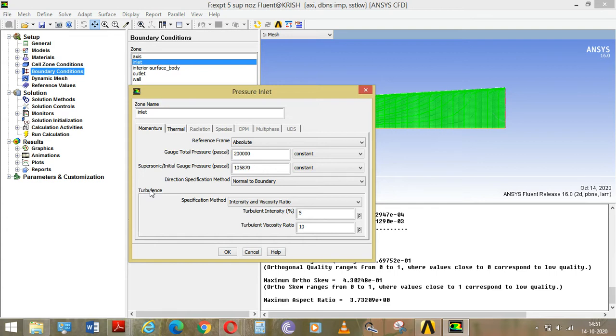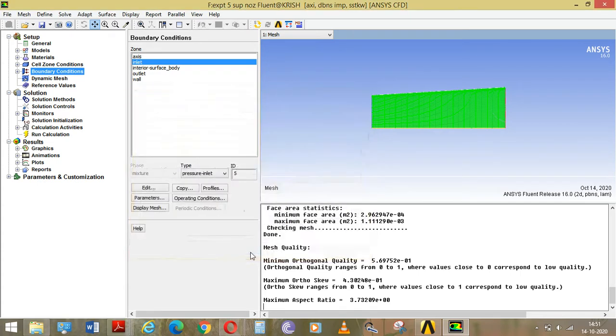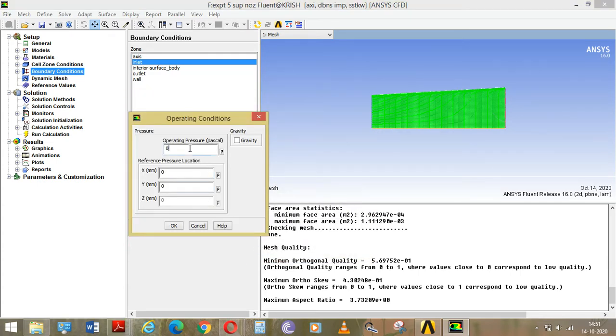So you already have a reference pressure of 1 bar. So you're already operating, that is a gauge pressure. You're already operating around atmospheric pressure 1. Okay, that is gauge pressure. So that is why the operating pressure is 0, because it's already included there.